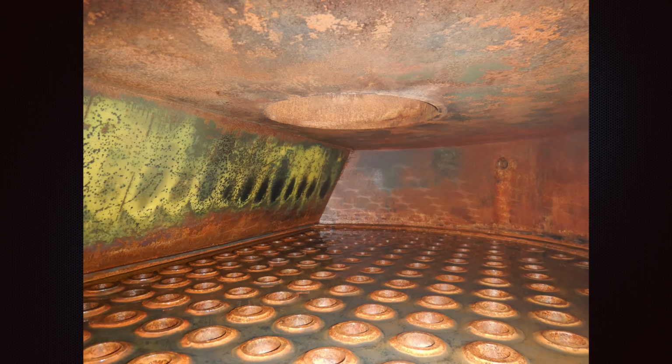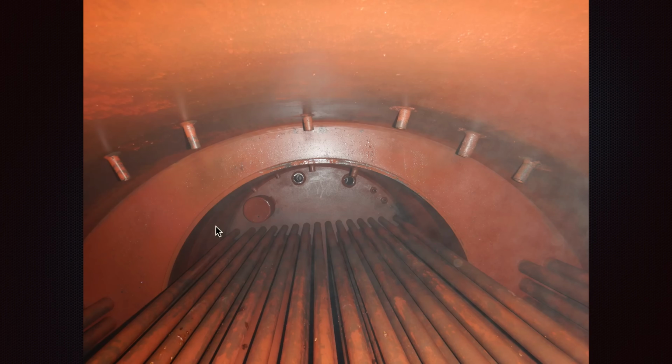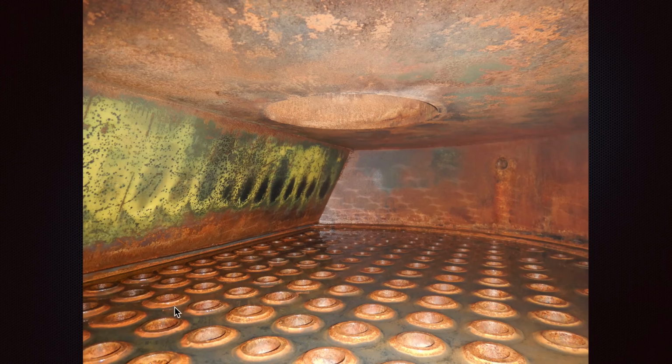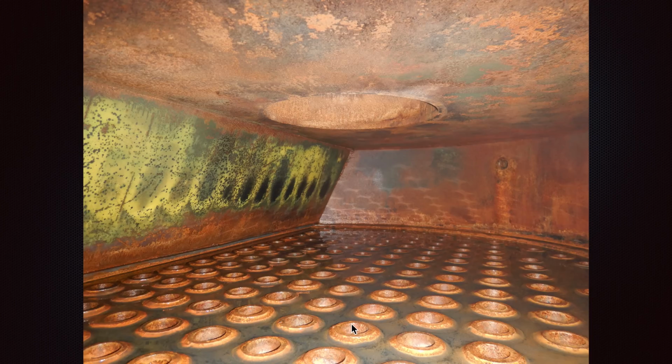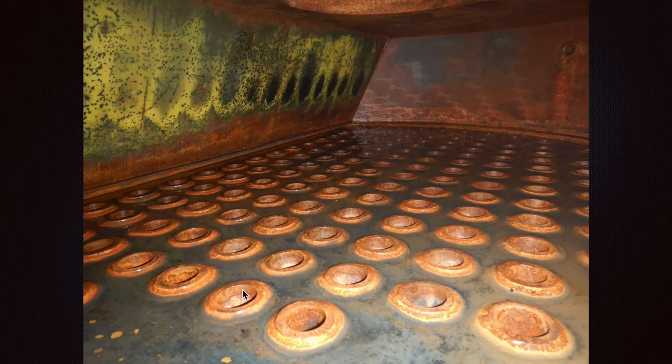Here we have the top of the tubes, so we are looking at this area on the top, and this is how the exhaust gases come out. You can see the sulfur concentration on the top, and all the fuel and exhaust gases go on the top here to the funnel. So any exhaust that is accumulated here, the main engine exhaust gas that is passing, needs to be washed, cleaned, so there will not be any back pressure created to the tubes.